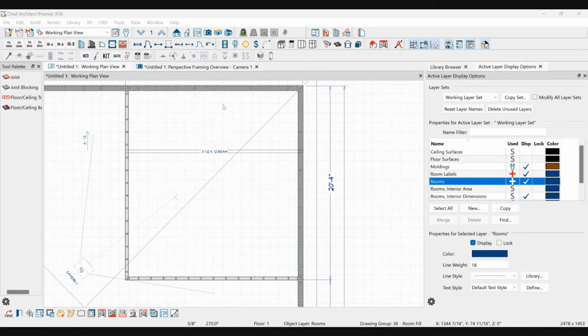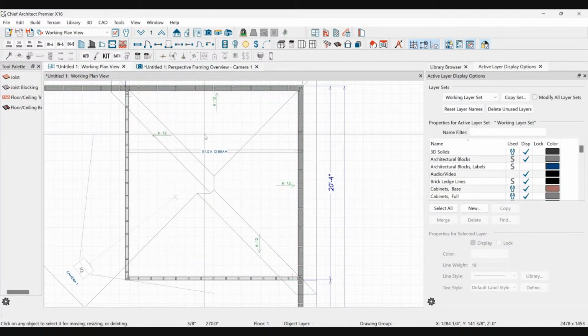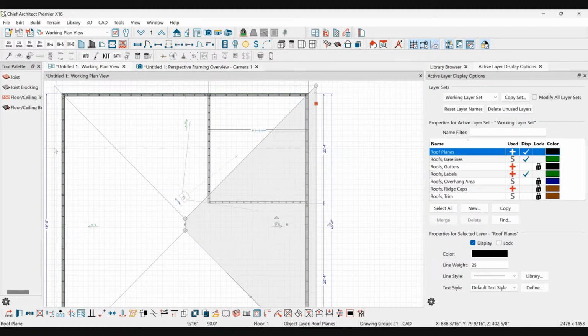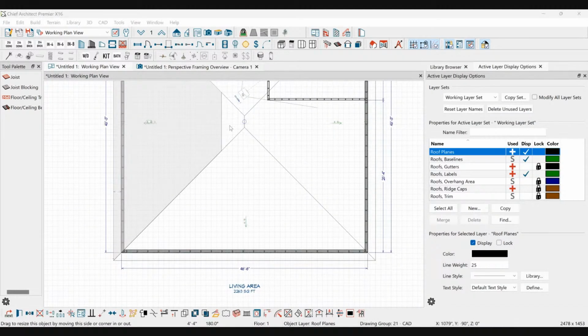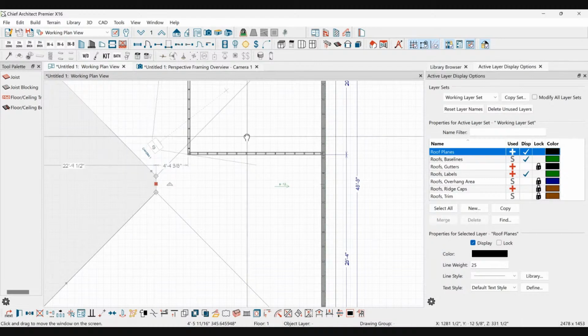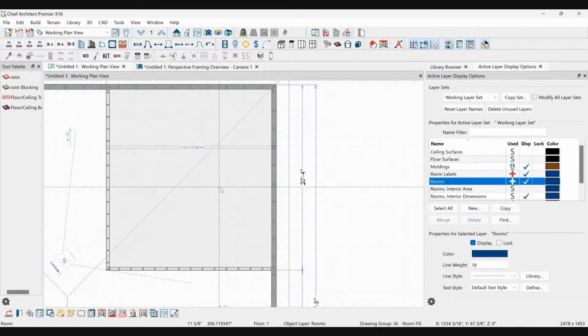I'm going to bump up my ceiling to a 10-foot, which is 121 and 1/8. And undo that, because I want my roof to stay alone, to not move. Let's do it by modifying something here. Auto rebuild is off, so my roof will be left alone. I'm going to take the structure of my ceiling and say 121 and 1/8.